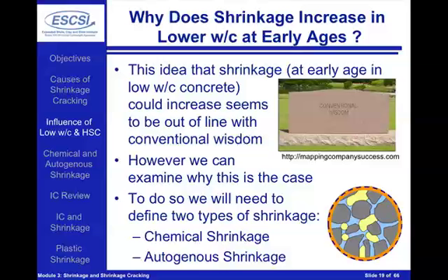So in lower water to cement ratio concretes, why is it that this shrinkage is high at these early ages? And again, I want to point out here that sometimes time has really passed on the conventional line of reasoning, or the conventional line of wisdom. And here we can start to examine why this is the case.